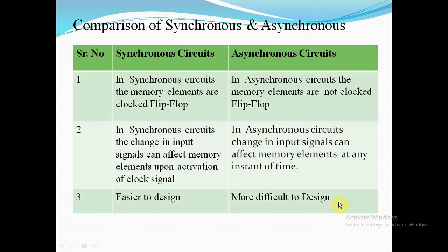The comparison is given here: synchronous circuits and asynchronous circuits. In synchronous circuits, the memory elements are clocked flip-flops, and in asynchronous circuits, the memory elements are not clocked flip-flops. In a synchronous circuit, a change in input signals can affect the memory elements upon activation of the clock signal. In asynchronous circuits, a change in input signals can affect the memory elements at any instant of time. A synchronous circuit is easier to design, and an asynchronous circuit is more difficult to design.